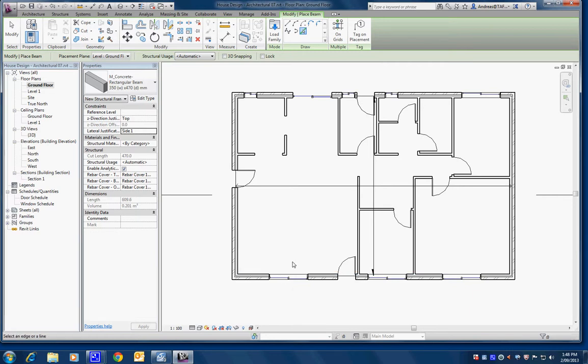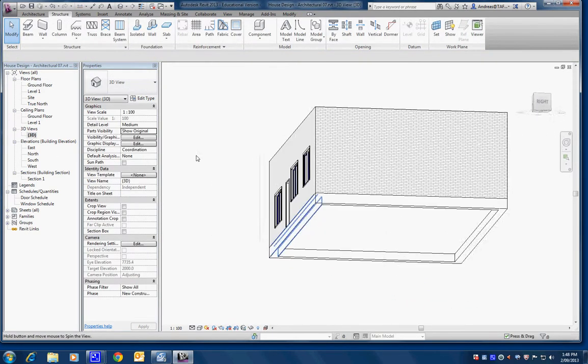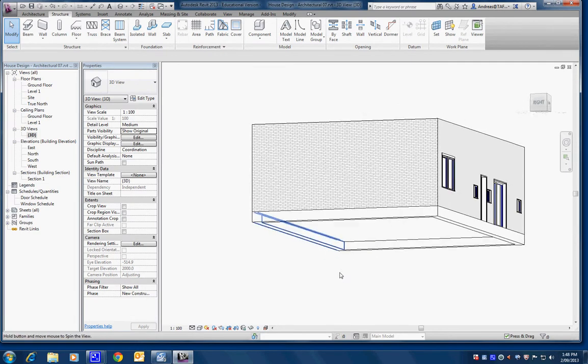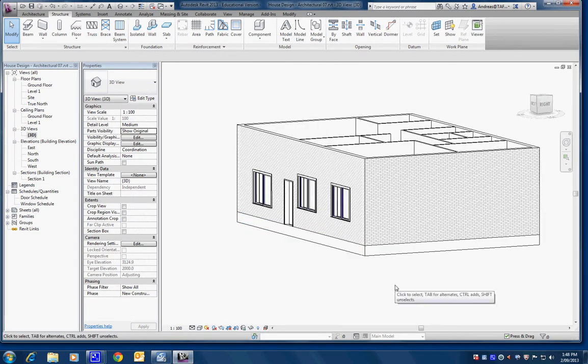I assume that worked. How do I know? Well, I don't know, so I have to check here. So I go here and I can see that it's under there. Alright, that's good. We're just putting the ring beam around for now, and we're going to see what we'll do with the rest when we do the structural. Alright, so that's the beam there. The thing is, it's supposed to be 30 millimeters below, and I think we haven't actually done that yet.